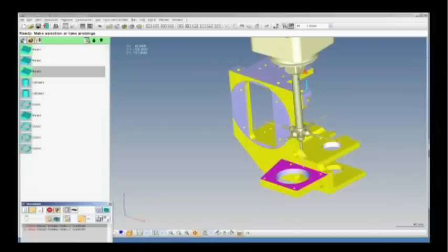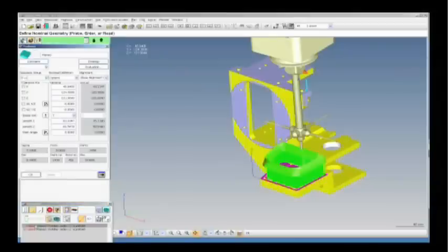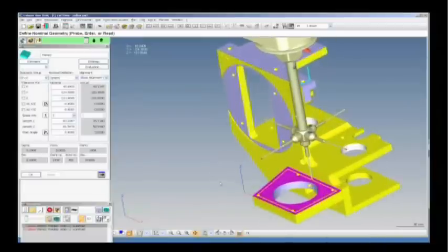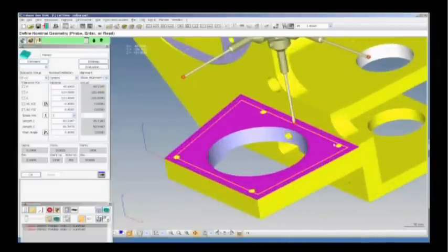It does some logic. It says solid meets solid. That's not good. So if I actually open this guy up, it's actually showing me the path that it is following, and you can see it's probably not the best path that we have on there. A better strategy would probably be to use that back probe, and maybe just scan the front of the part here.